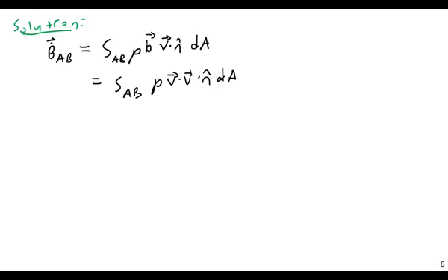So the overall momentum flow rate would be something like kilograms meters per second. And if I look at this in terms of its intrinsic property, in other words, divided by mass, I effectively get just meters per second, or simply velocity. So that's why, if the extensive property is momentum flow rate, the intensive property, the momentum per unit mass, is simply velocity. So that's why I have two different velocity V's here.